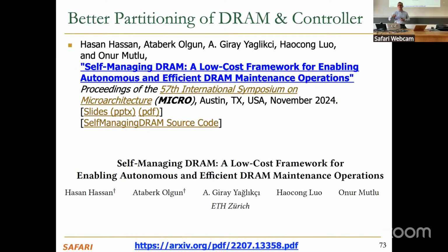What do you mean, refresh the cache? Which cache? Let's say I access one cell. If I were to access a cell which is adjacent to it, the next access will happen from cache, and there is no possibility of RowHammer. But if I were to access something which is not in the cache, then there exists a possibility of RowHammer. So what I'm suggesting is, instead of modeling things for access in the loop, what if we model it on the basis of reusability in the cache?